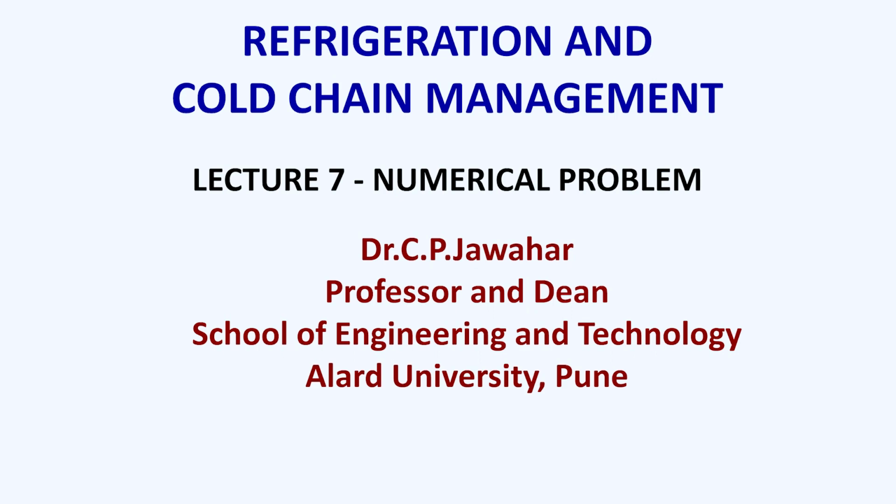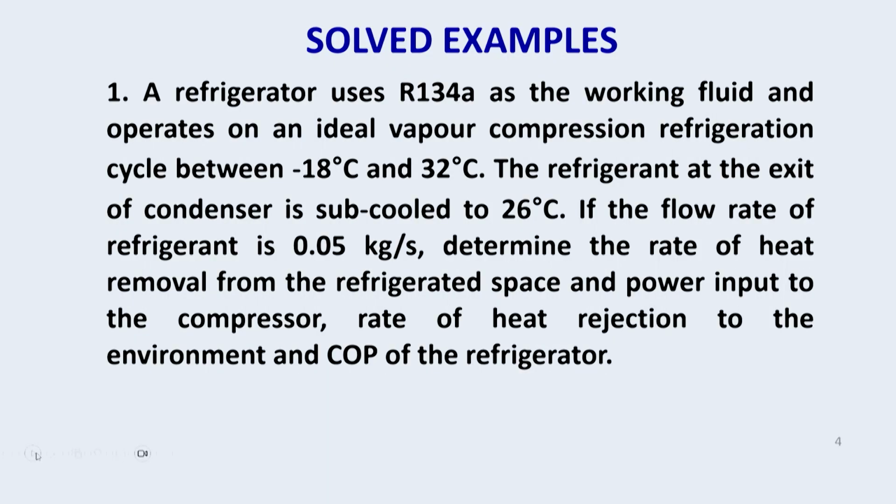Welcome to lecture 7, numerical problem. In this lecture, we will be solving a numerical problem based on the vapor compression system with subcooling. This is the numerical question. The evaporator and condenser temperatures are given. Evaporator temperature is minus 18, condenser temperature is 32.